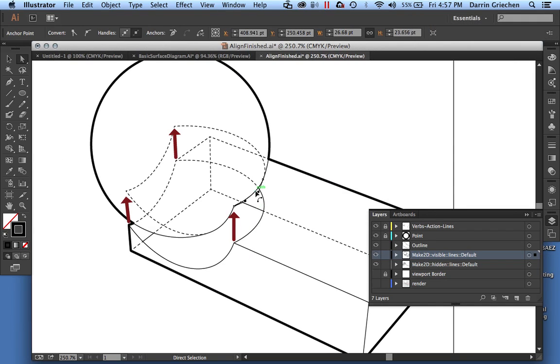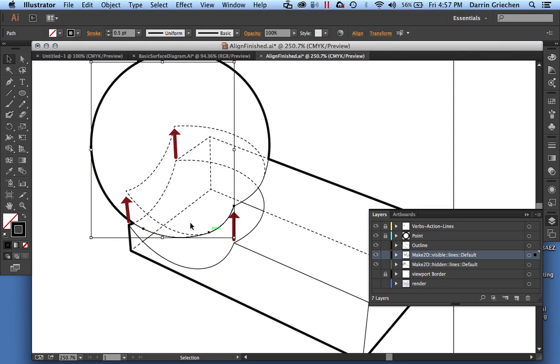In terms of line weight, we have some exposed edges, and exposed edges usually have a little nicer, a little thicker line than these edges here. So you can go in and add some thickness on here. In this case, it's not that big a deal for the moment, but we might bump that up to like 0.75, just to make that pop just a little bit more.